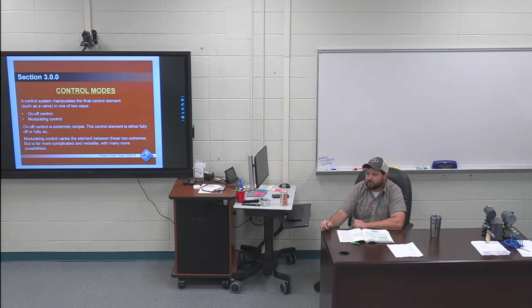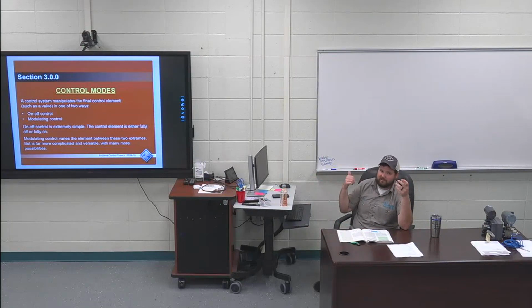Modulating control. So if I had a big control valve that can operate between 0 and 100%, that would be modulating control. Like I always say, you've got your big tank, you're filling up to 500 gallons of water. You need some water, but not a lot. That control valve can open up to 50% to start giving it some water, and as it gets closer to that 500 gallon set point, that valve will start to taper off, like 40%, 30%, 20%, so that whenever it gets close, it slowly gets there and it's not having to shut off immediately. That makes sense? That's modulating control.